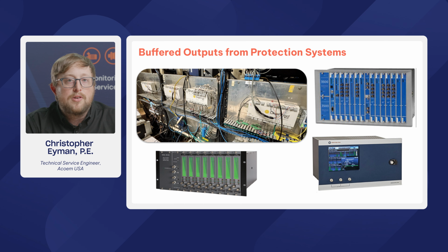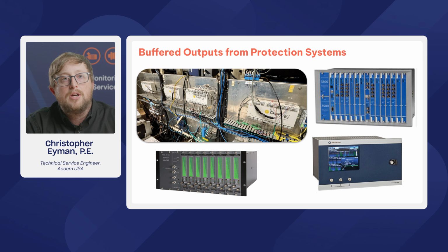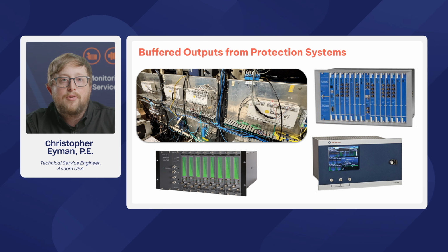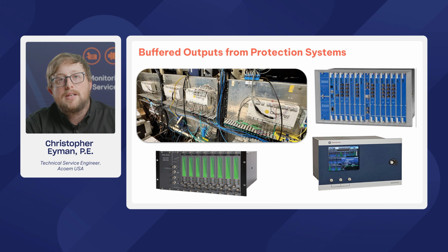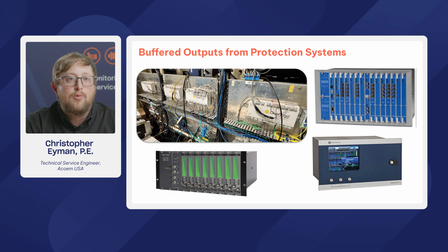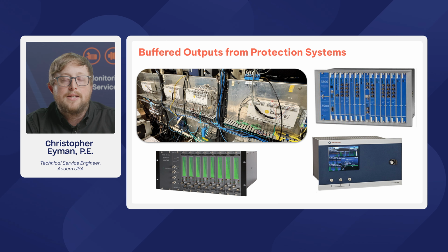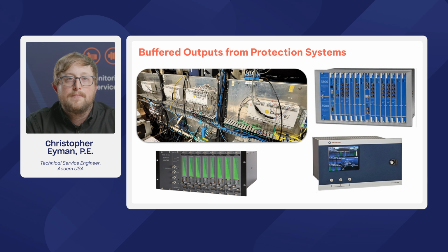Sometimes size constraint is also important, but the other thing is we can attach these systems onto pre-existing protection systems or field-mounted accelerometers that you may have put in for a portable system, and we can take that data into our wired system and feed it into our database. So we can have the protection of a protection system where it shuts down the equipment, and we can also analyze the data to be proactive with our maintenance schedules and our maintenance solutions.